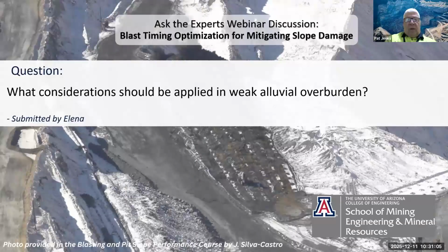As you maybe transition from a non-cemented material to a cemented one, having good, sound geologic and geotechnical exploration to identify where those cemented zones are located in the subsurface will help you better transition from where you might be able to free dig to where you might need to shoot that cemented material in order to load it with your loading equipment. So those are some of the things I would suggest that people consider.